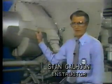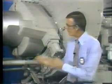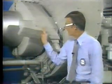The variable vanes move between two positions to control the amount of air flowing through the compressor. Engine stall is prevented by matching the amount of air entering the compressor with the amount of air leaving the compressor. This air flow is regulated by the vanes, thus preventing engine surge.